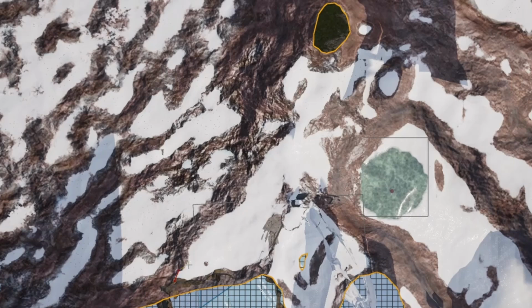Now I click space, and you're just clicking space. You're not left clicking. And then you see I'm just gonna follow this ridgeway. I think it's going to create this volume down further on the Z axis, so I'm gonna try and get a little bit further into the snow so that my player doesn't accidentally fall. It doesn't really matter how thick it is. I'm just gonna go out this direction and then create the full shape, and then you see how it auto connects. Then I'm going to click the enter key, and now it creates an actual polygon shape.